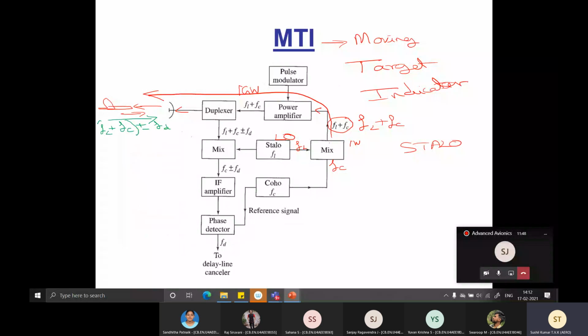So the transmitted signal is reflected back, a portion of it, with a Doppler shift, or phase shift. Frequency and phase, rate of change of phase is frequency, so you can interpret it either way. So there is a change depending on the velocity. Now this Doppler is related to the velocity of the aircraft, and whether it's approaching or receding gives the sign of the shift.